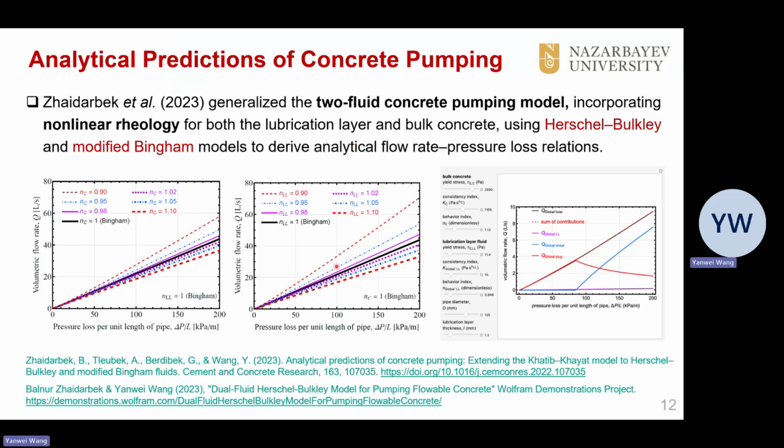Those results illustrate how changing the non-linear parameters in the bulk concrete and also the lubrication layer fluid affects the pumping pressure flow rate relation. And this shows that the rheological nonlinearity is not just a minor detail. Actually, it affects the pumping prediction quite dramatically.